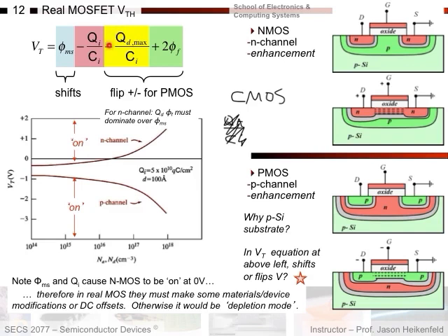So I get a positive and a negative. The net term here is negative. Before, the net term was positive. Now it's negative, so this switches signs when you do PMOS. Just trust yourself in terms of what is the depletion charge itself, and just put it in this exact same equation, and you'll find that it counteracts this negative symbol or it doesn't.